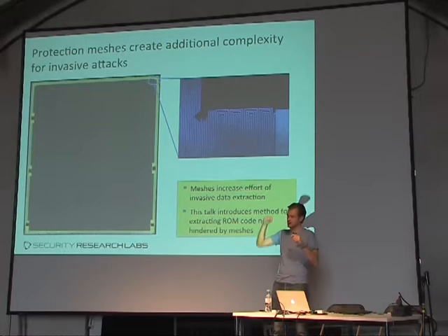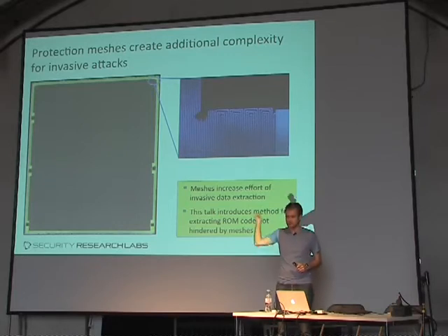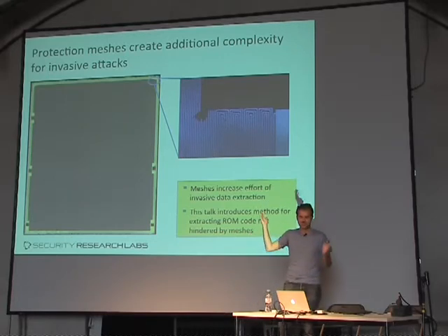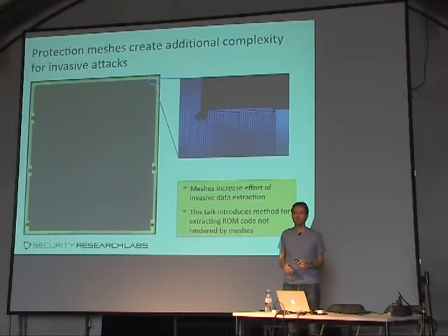Right? So it will never put any secret information on its little wires. If you try to get with your needle underneath this mesh, this prevents the chip from exposing sensitive information. And today these meshes are a little smarter. They're like interleaved snakes with pseudo-random patterns among them. But there's always a way, of course: finding the 2 points that should be connected and connecting them in another way, not through this mesh, and then drilling your hole in the middle after all. But that's what Kristanovsky specializes in.